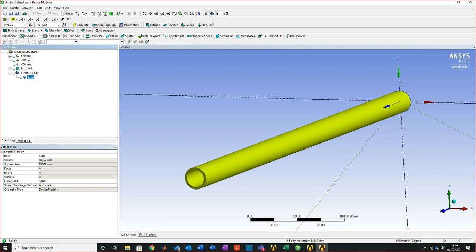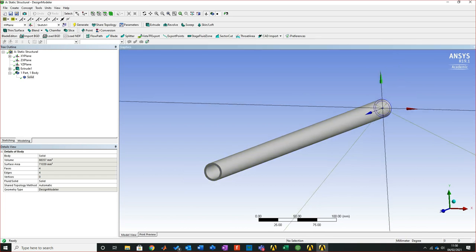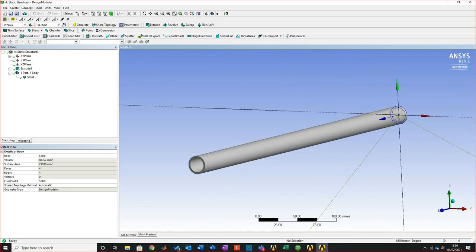If you've done anything a bit shoddy in your design when you import it, ANSYS won't be able to resolve it, and it will turn what could be a basic part into 50, 60,000 surfaces, because some of the surfaces will not be resolved and it will be left open. There's ways of patching that, there's ways of fixing that, but that gives you a big insight. You notice here it's even brought in a new CAD importer. So under your CAD importer, you've got all types of different things you can try and make it work better, but it's one of them things that a lot of people have tried to do for many years to try and get it working nicely.